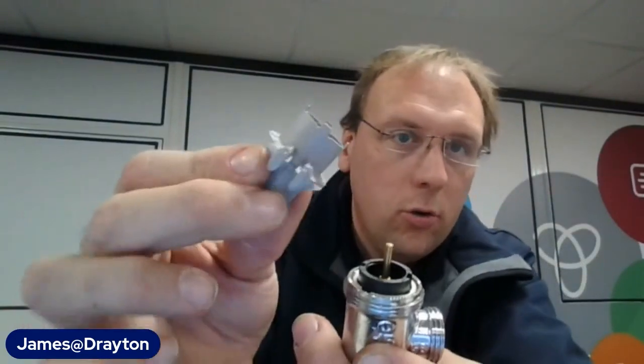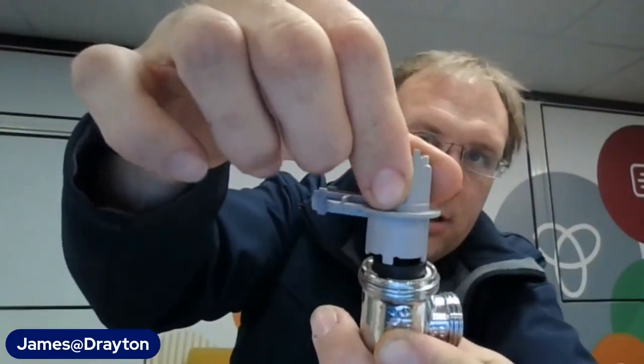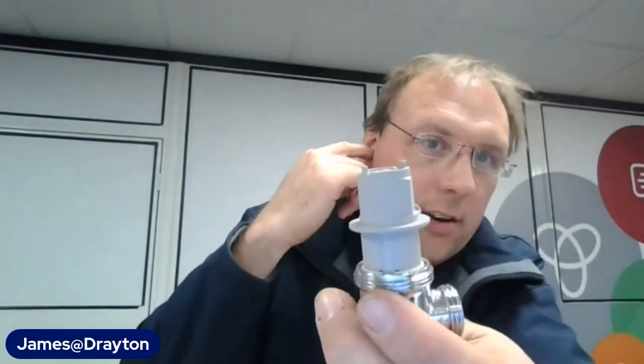Now, the way we do this is obviously you can't afford to take the clamp ring there completely out, because if you do, there's nothing holding the insert in. So the way that you do the balancing with these is you use the tool, you insert it, and you can turn it around about 180 degrees.